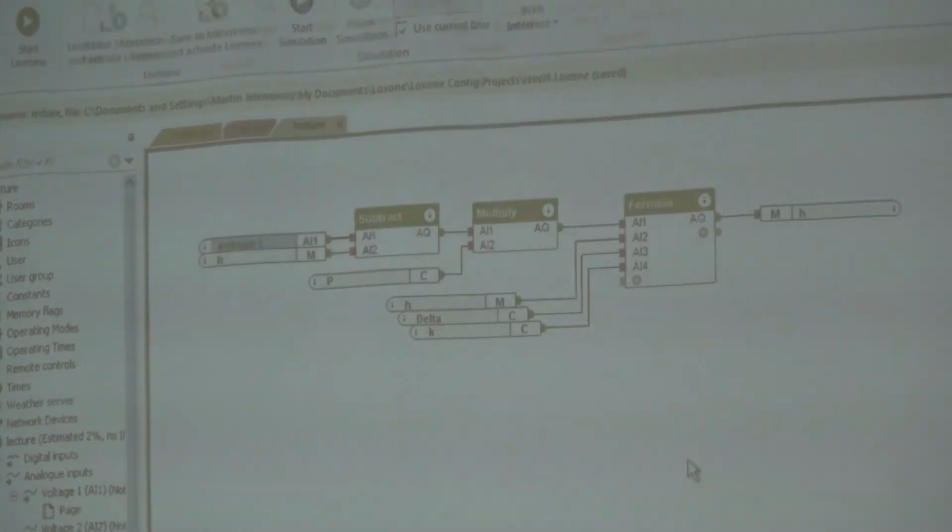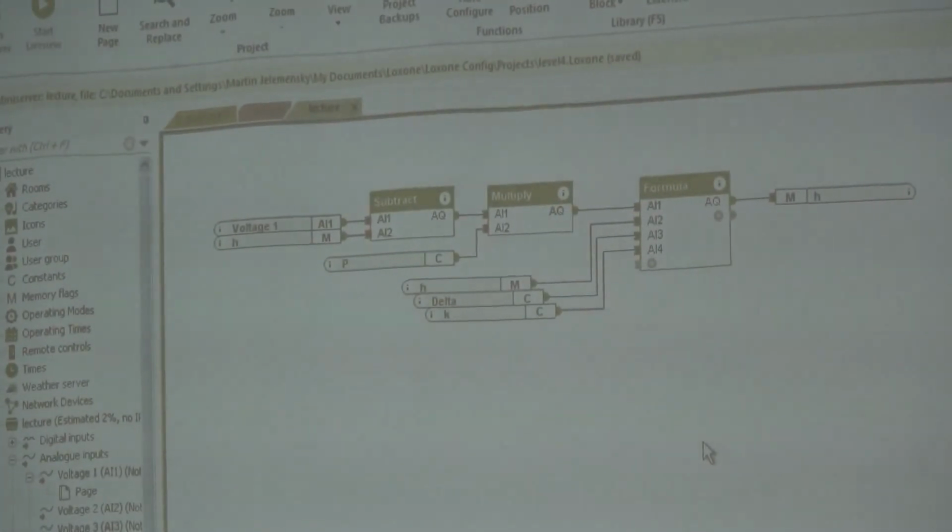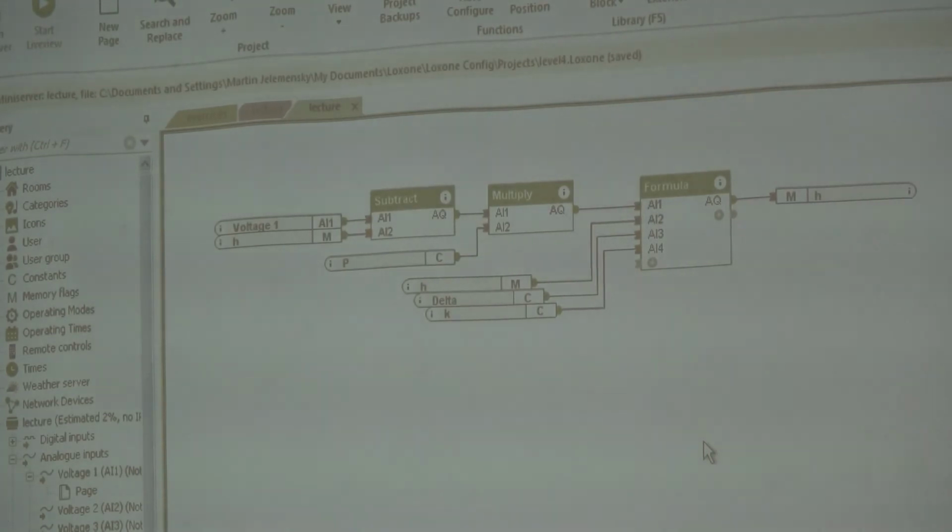Well, actually, it is not as bad as it sounds, because of course PLCs come with pre-configured PI and PID blocks. There you just set up what the gain should be, what the integral and the derivative time constants should be, and it's really just a single block. So let's hope this works now.